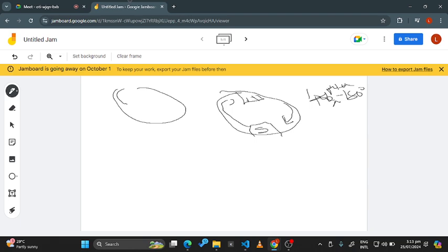Then the total electrical degrees we are going to have is one pole pitch plus one pole pitch, which is two pole pitches. And if a pole pitch is 180 degrees, two pole pitches will be 360 degrees. In this case, we have 360 degrees electrical equal to 360 degrees mechanical. Is that okay?